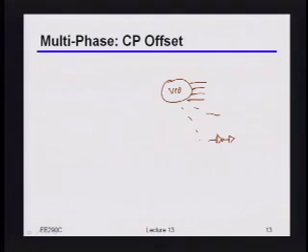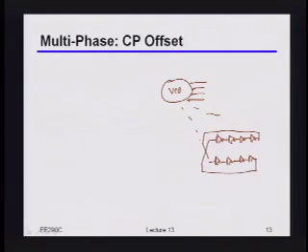So what they basically do is they say, well, okay, look, if I've got some VCO that's sitting inside of a PLL, well, if I can just somehow nominally move the phase of that VCO around, then automatically, if I really have a multi-stage ring oscillator, you should keep in mind that what's inside of here is just something that conceptually looks like a bunch of inverters tied back to back. Okay, and I'll draw it so there really are 4 phases here. Right, so something that looks, say, like this.